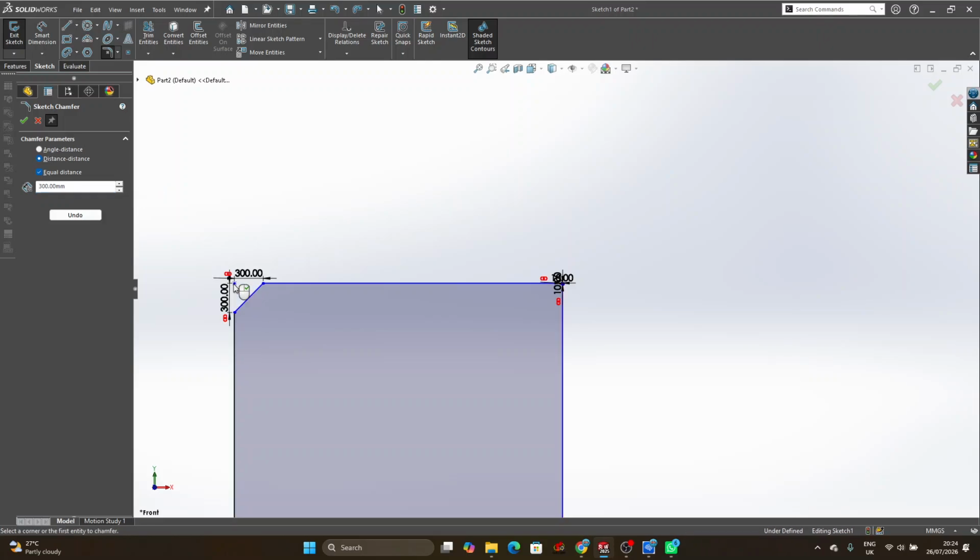and can you see? It's propagating 300 millimeter to the left, to the right, and also 300 millimeter downward from the edge, from the initial edge. So that's what the chamfer does. It just cuts it, like it cuts to the edge and makes it angular.